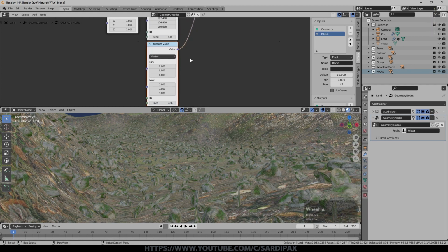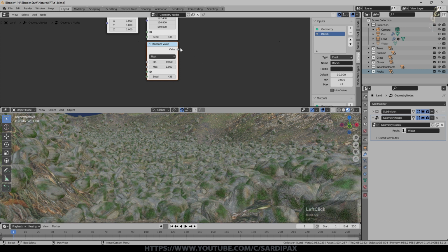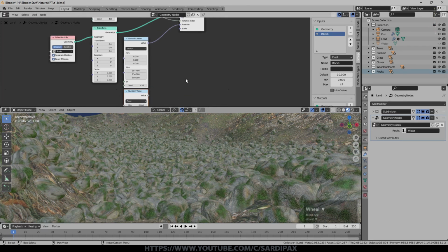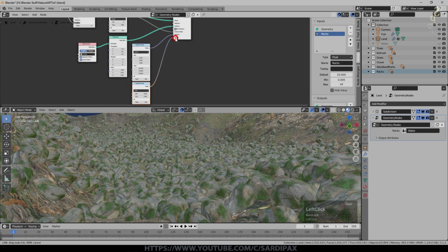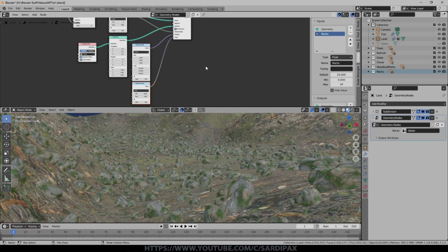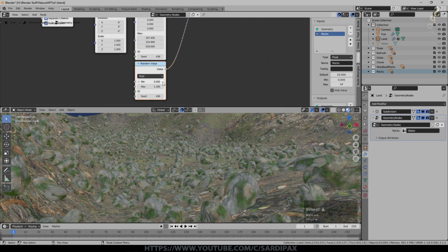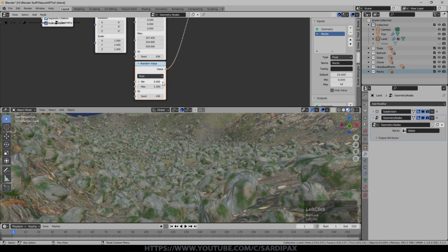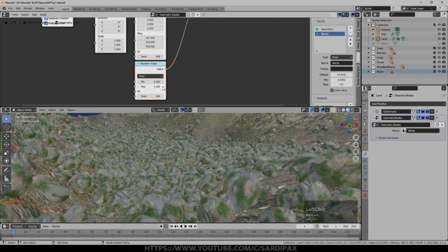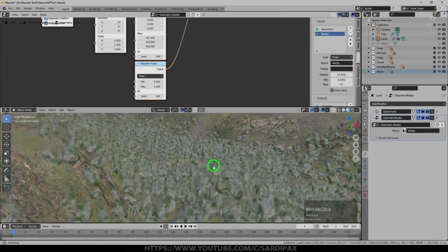And a quick and easy way to do that is to simply change this to float. So it's only providing one value, but luckily Blender just says, oh, you put a float into a vector, you must mean the same number into each. So I can now increase this. So the minimum is 0, and I obviously don't want 0, there's no point. I want it to be big enough to be seen, and then the maximum, whatever I find is about right.